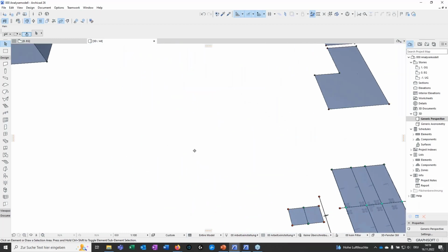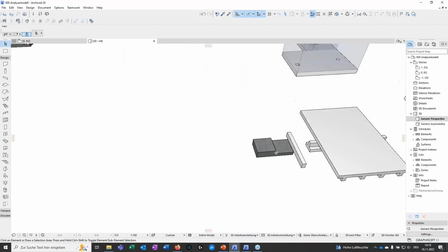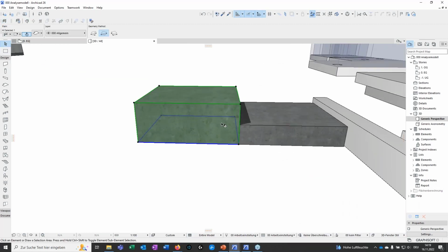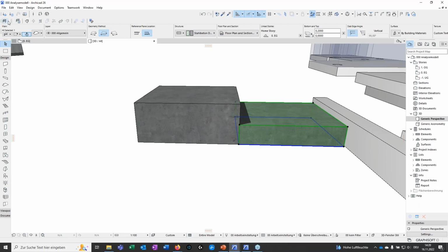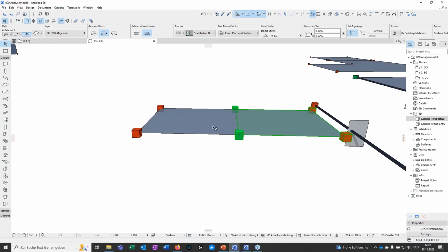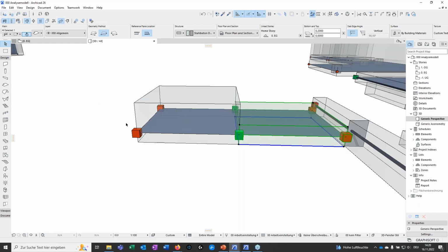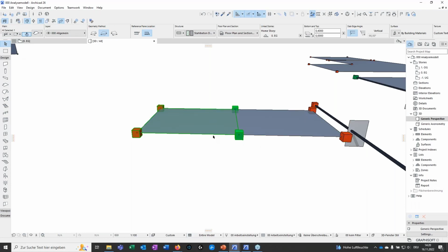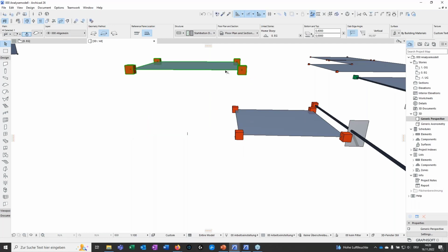In the next step, often you have slabs of different sizes. And there you have normally the problem that you want to have the whole flat on one level. And so you can add this once with the rules, and in the other way you can edit this when you take the slab and grab it and change it with the mouse.